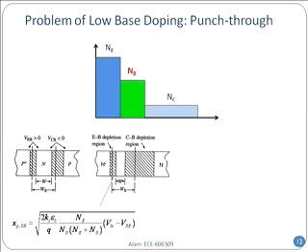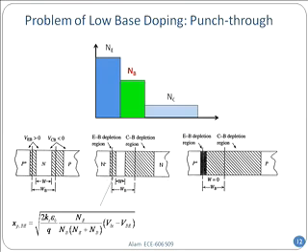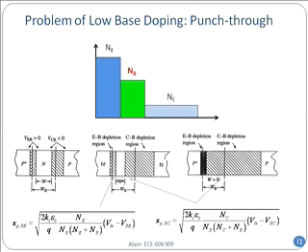This is not much of a problem. It's a forward bias junction. If anything, it's better compared to zero bias. It's a little smaller. Depleted region is smaller. But what about the collector? Well, on collector, you have applied a huge reverse bias. And as a result, it will be sort of eating up in that region a huge fraction.